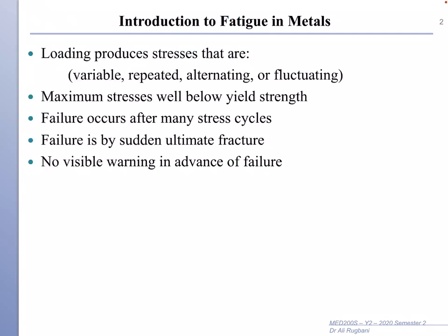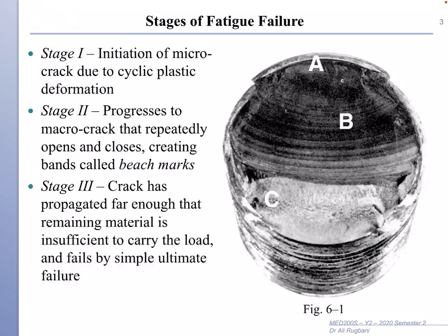When we have dynamic conditions, failure can happen even if stresses don't exceed ultimate strength. So failure happens after a few cycles of changing load, and failure in this case is sudden. You don't get any indication, there is no warning, there is no visible indication that failure will happen. So failure is complete and sudden failure.